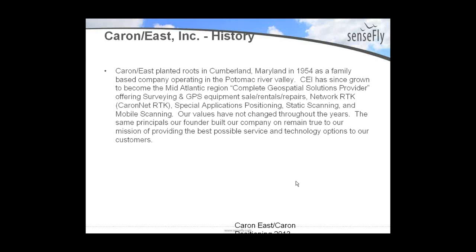I was able to bring in the point cloud inside of Point Tools, and I was able to bring in the ortho TIFF file in the CAD package, and then able to draw whatever I drew, polylines, points, and so forth, from Point Tools into the CAD package on top of the ortho photo, which is extremely handy.